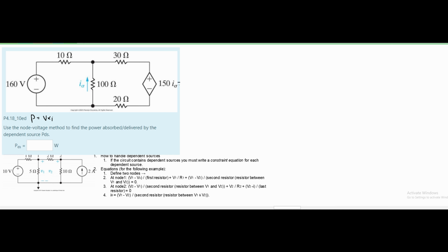Well, we know this is equal to our voltage. So we need to find our I naught. We need to find the current flowing through here, and that's a perfect setup for our node voltage method. So starting our node voltage method, we have to pick a node. This is the node I'm going to be working with, and we're going to start out by looking at the step 2. I've also included this little picture right here, as well as the steps to solve this specific example.